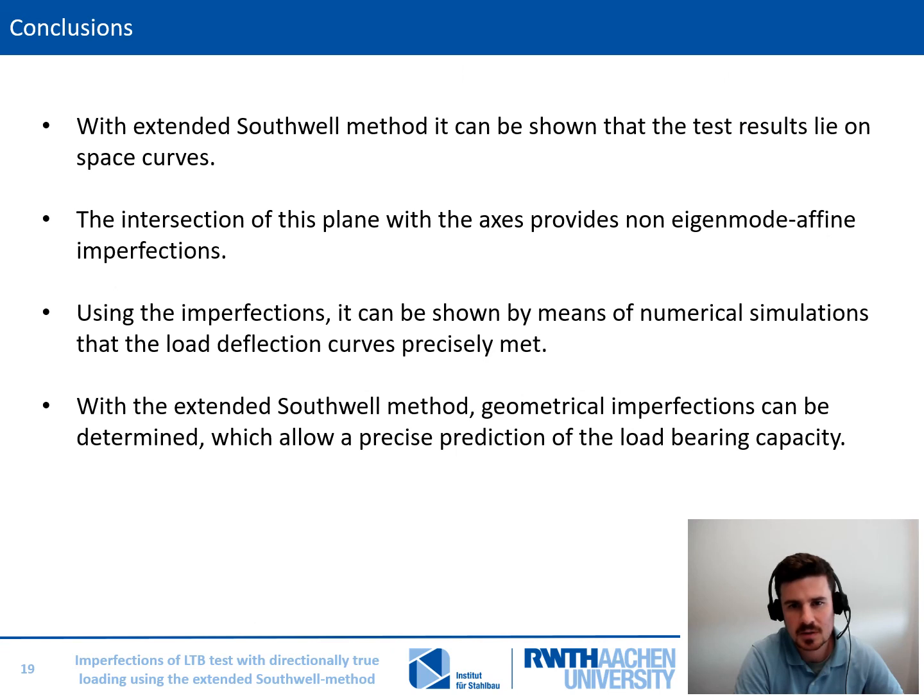With the help of the extended Southwell method, it can be shown that the test results lie on space curves, which in turn lie in planar skewed planes. The intersection of these planes with the axis provides non-eigenmode affine imperfection, similar and analogous to the application of the Southwell method on axially loaded members under compression. Using this imperfection, it can be shown by means of numerical simulation that the load displacement curves are precisely met. With the extended Southwell method, geometrical imperfection can be determined, which allows a precise prediction of the load capacity.